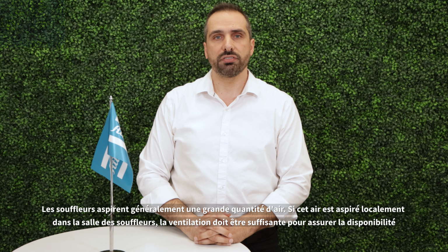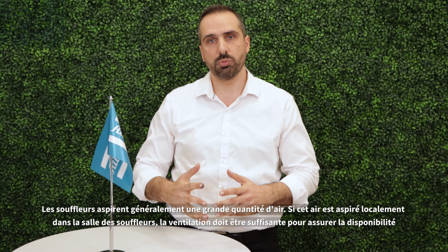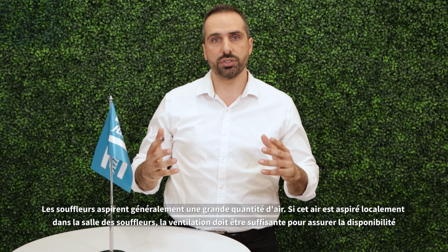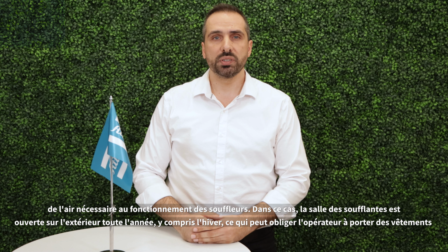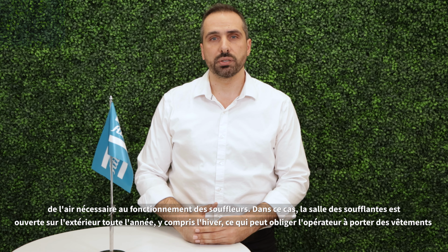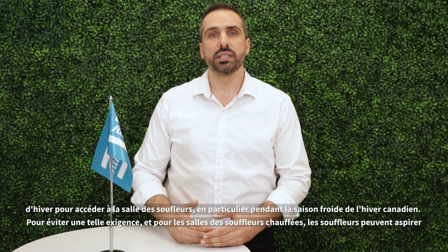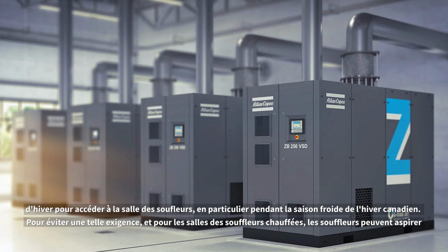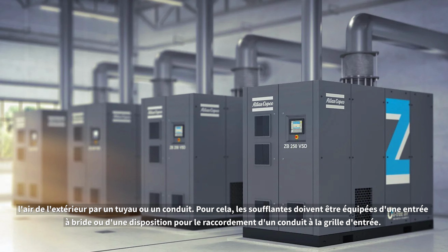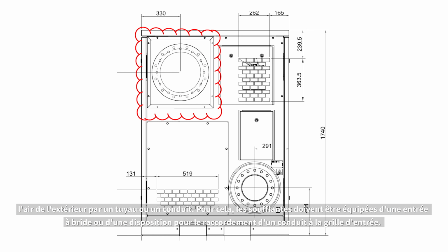The second option is inlet flange. Blowers usually draw a large amount of air. If drawing this air locally from within the blower room, there must be enough ventilation to make sure enough air is available for the blowers. In this case, the blower room would be open to the outside during the whole year, including winter, and therefore may require the operator to wear winter clothes to get to the blower room, especially during cold Canadian winter season. To avoid such a requirement and for heated blower rooms, blowers can draw air from the outside through a pipe or duct. For this, blowers should be equipped with a flanged inlet or should have a provision for ducting connection to the inlet.